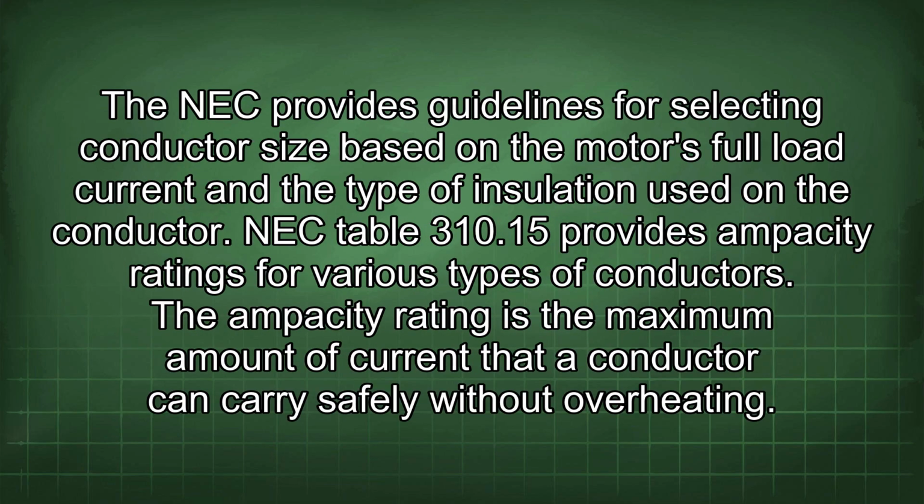To further delve into specific calculations, let's explore how to determine the appropriate conductor size for a motor circuit. The NEC provides guidelines for selecting conductor size based on the motor's full load current and the type of insulation used in the conductor. NEC Table 310.15 provides ampacity ratings for various types of conductors. The ampacity rating is the maximum amount of current that a conductor can carry safely without overheating.